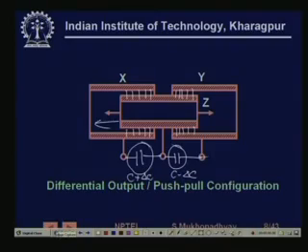You can either push it or pull it, and as we shall see in our signal conditioning lessons, there are certain benefits if you have push pull configurations in terms of nonlinearity as well as in terms of sensitivity. And also sometimes tolerance with respect to other kinds of inputs, like interfering inputs like temperature, etc. So for these reasons, sometimes the push pull configuration is preferred, and this is a push pull configuration for capacitive motion sensing.